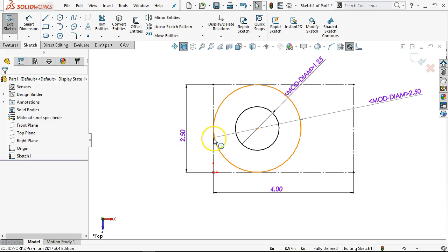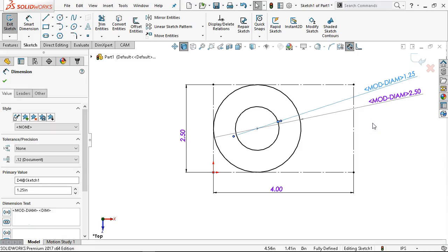I may have what-if scenarios where I'm not sure if I want the relations or the dimension to be the priority, or multiple dimensions to be the priority, in which case I can switch out driven for non-driven and cycle through them to see what scenario is going to work best. So that's kind of an advanced thing, getting into the logic and the background of the dimensions. But maybe I want to keep this and have it there for visual, and then be able to switch back and forth depending on my conditions.